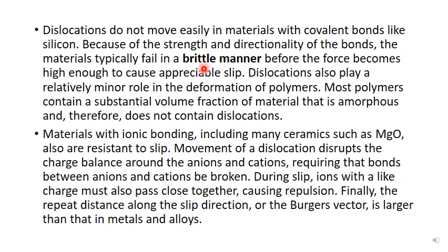Brittle fracture means that the material, after passing the elasticity limit, exhibits very limited permanent deformation before fracture. While ductile fracture, which is normal for metals and alloys, the material exhibits a long plastic deformation after elastic deformation, a large amount of change in the dimension before fracture.